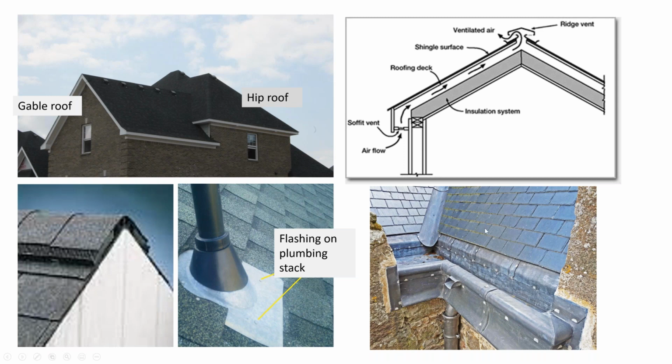This is a slate roof with a box gutter actually. This is flashing. You're going to hear about this a lot too on your home inspection reports. These rubber boots, which is what this is called, they tend to crack up over age. A lot of times they will suggest you put a lead boot. The lead will last a whole lot longer. However, squirrels love lead. So if you have any trees nearby your roof and you have lead boots, you're going to replace them every few years because the squirrels get up there and eat them for whatever reason.